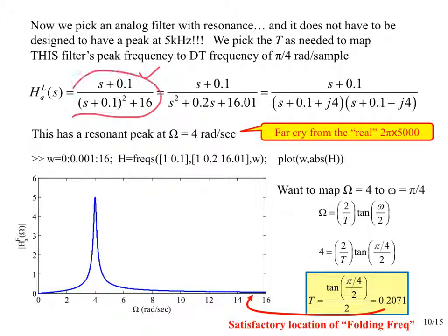This structure is something that we know, and other signal processing people know. Okay, that'll give me a resonant peak. If I expand out the denominator, I get that. If I factor out the denominator, I can now see, oh yes, I get a resonant peak at omega equal to 4 radians per second, and with the real part being fairly small, my poles are fairly close to the unit circle, and so that's going to give me a resonant peak.